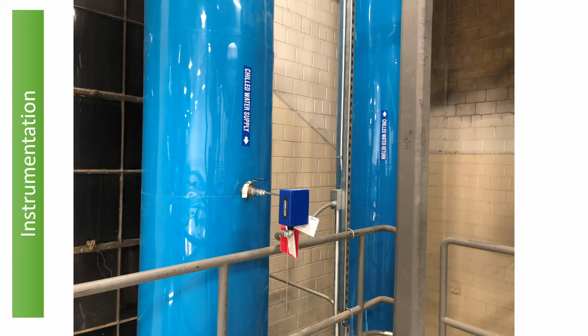So here we are. This is the east side piping. So this chill water line is going down into the ground, and these are basically buried. They're kind of direct buried. They're not in a tunnel. They're direct buried to make that giant loop around campus that we talked about. So this is the pipe going out, and then this is the water coming back from the giant loop around campus. So supply and return.